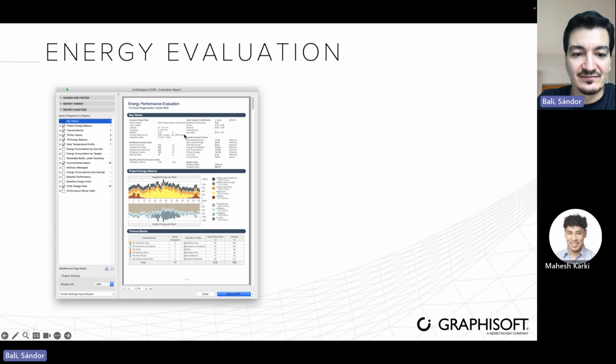And basically, these are going to be the most important values here. An overall U value for the building shell average. I think probably this is very standard worldwide, that there has to be a value that is not higher than this one. Here you can see the primary energy consumption, fuel consumption, the degree days, which is going to be a good indicator whether it's a heating or cooling dominated environment for our building. And then you're going to see the project energy balance.